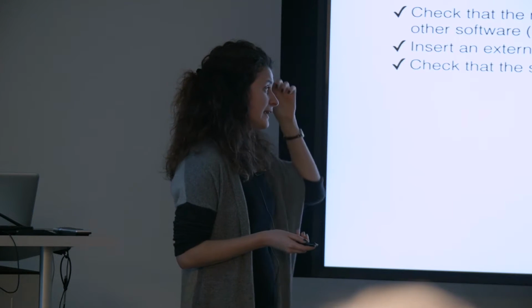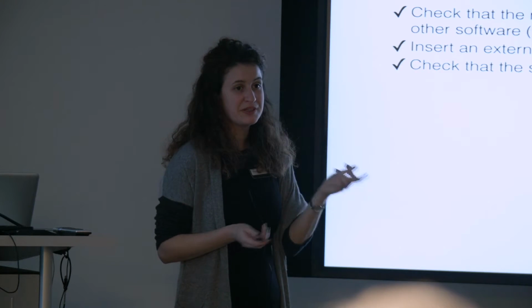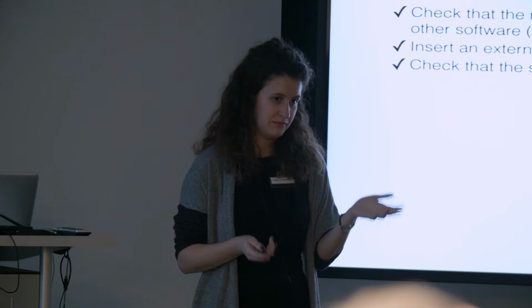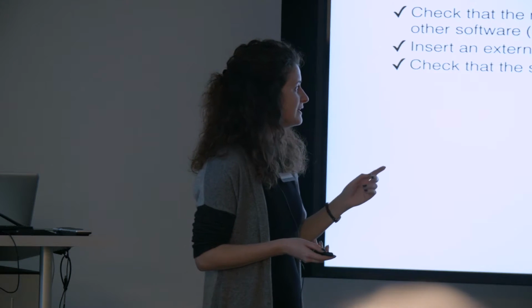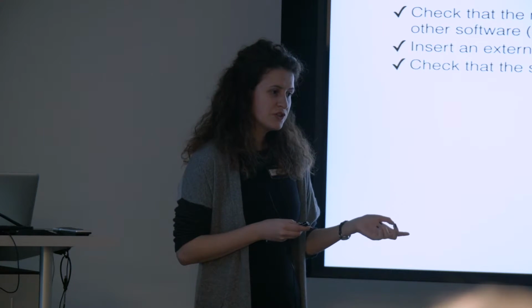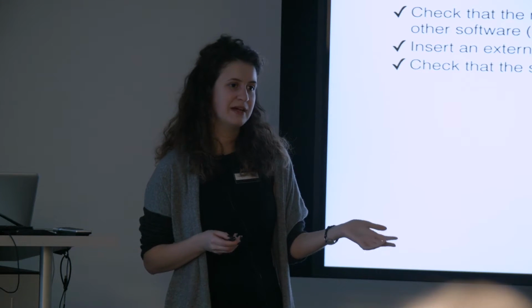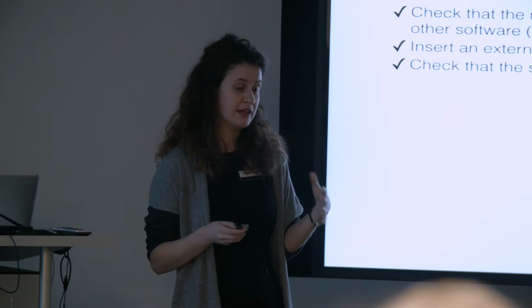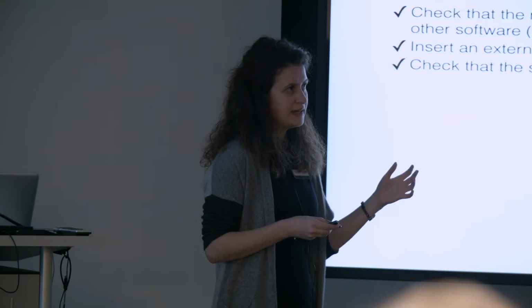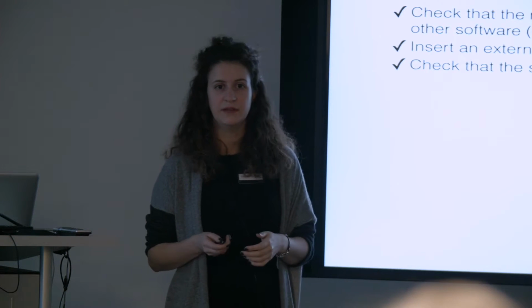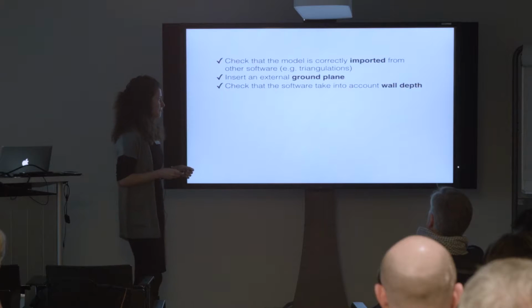And then, the wall depth is important in lighting because we have a reveal that could bounce a good fair amount of light. But some software don't show it, especially if they are building simulation software. For the energy part it's not strictly needed, so they are not showing it to you, but they actually, like OpenStudio, add it afterwards. So check in the manual or somewhere that it is doing that.